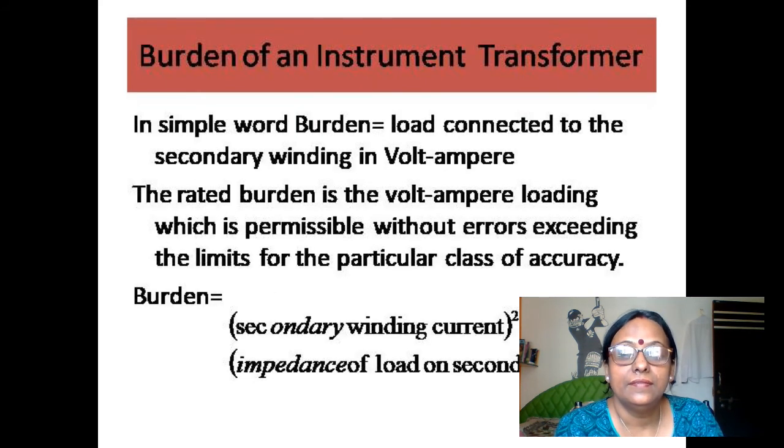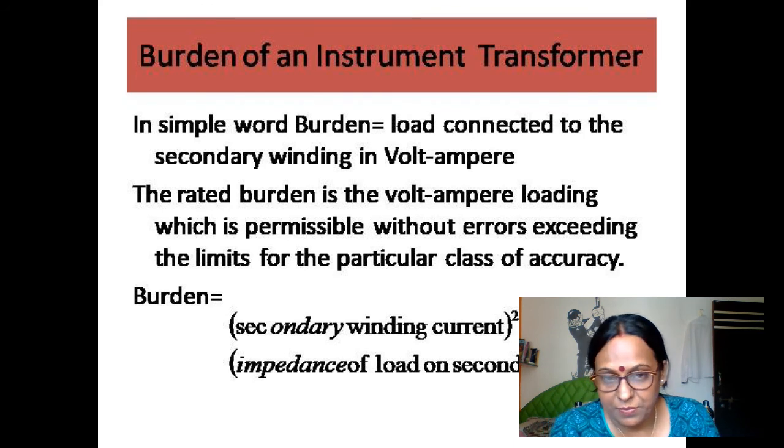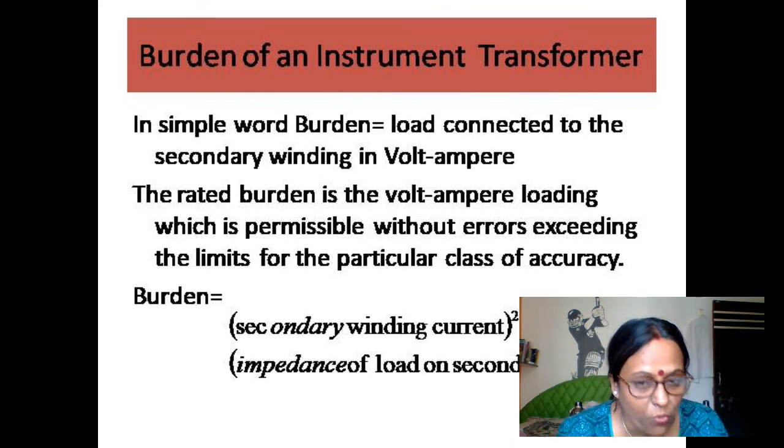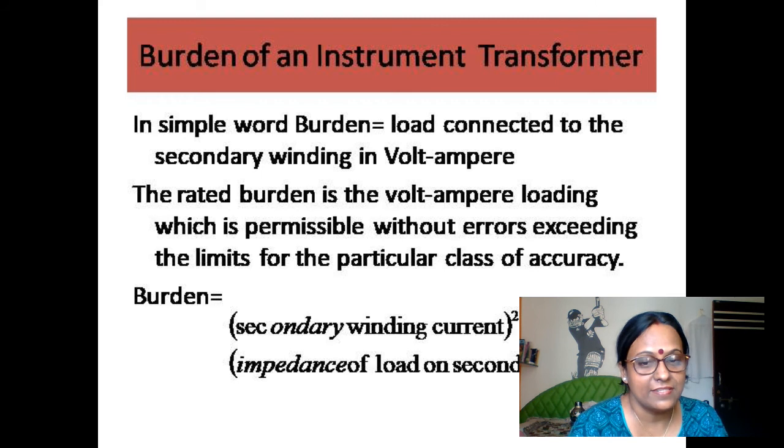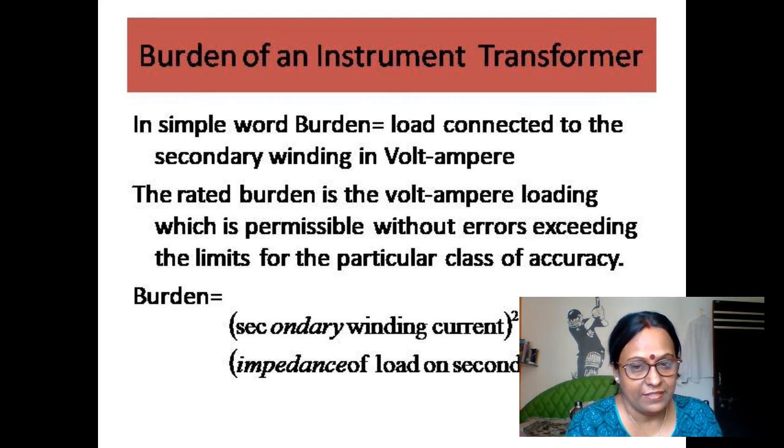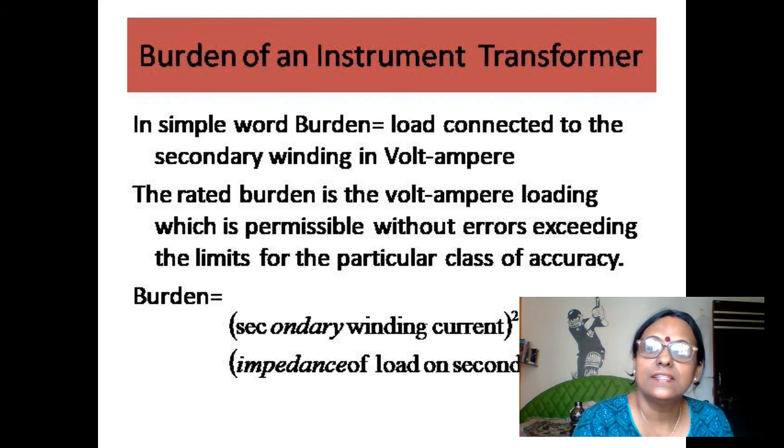Next, what is the burden of a transformer? Burden means it's the loading, that is, a load connected to the secondary terminal. So, in simple words, burden is the load connected to the secondary winding in volt-amperes. The rated burden is the volt-ampere loading which is permissible without error exceeding the limit of the particular class of accuracy.